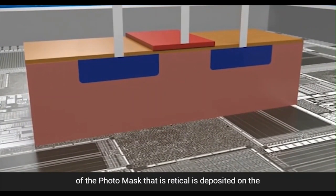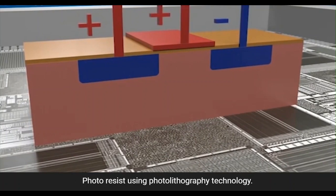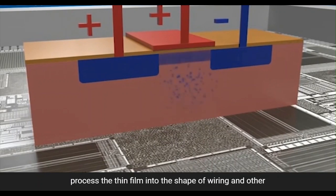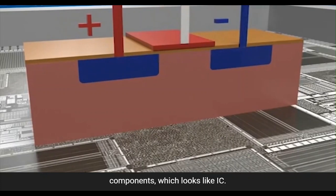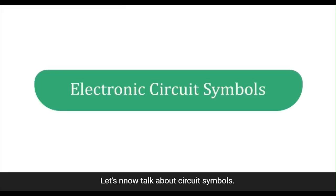The circuit pattern of the photomask, that is reticle, is then projected on the photoresist using photolithography technology. The developed photoresist is used as a mask for etching to process the thin film into the shape of wiring and other components, which looks like an IC. Wow, the world of electronics is just mesmerizing.